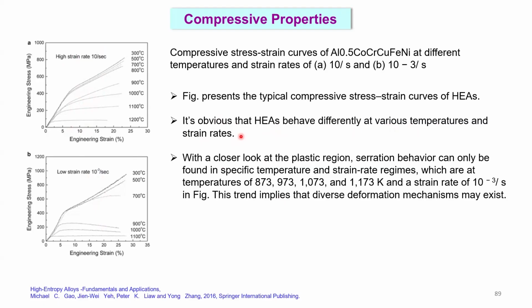Okay. So, if you look at the metallurgical literature, the material behavior at a high temperature is always correlated with the high strain rate. The kind of property you observe at a high strain rate, you will also expect at a high temperature. It's a kind of an idea.